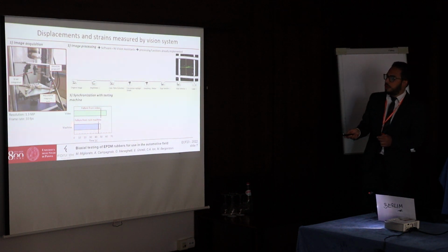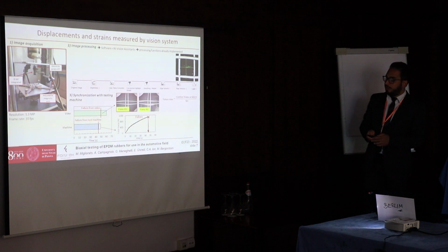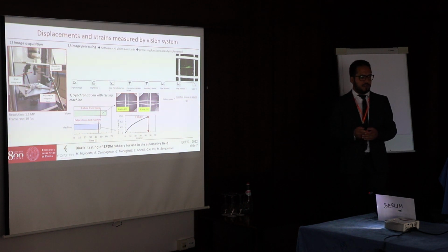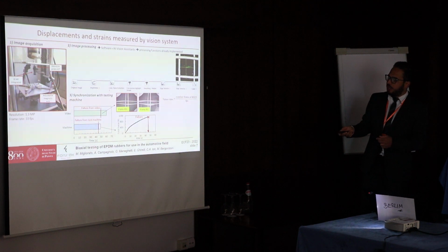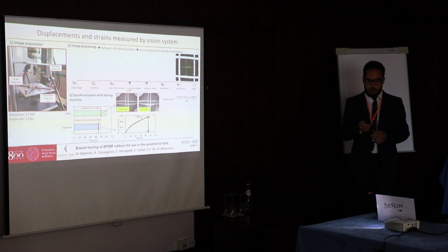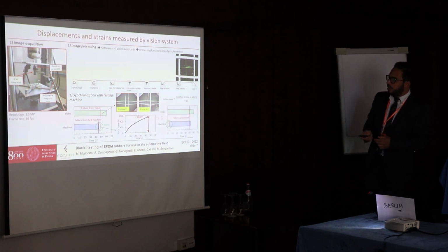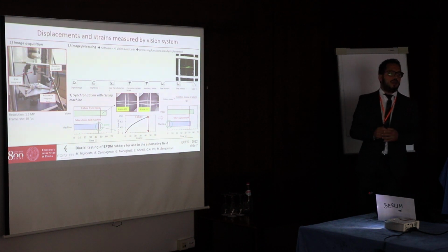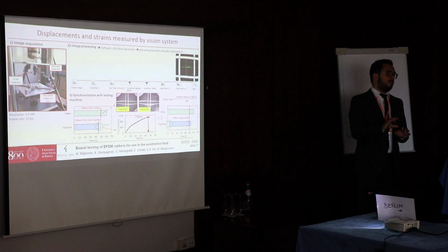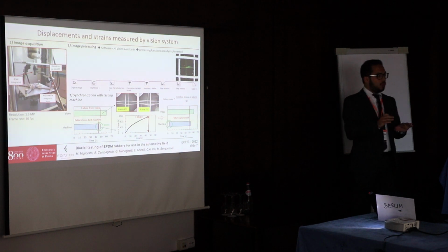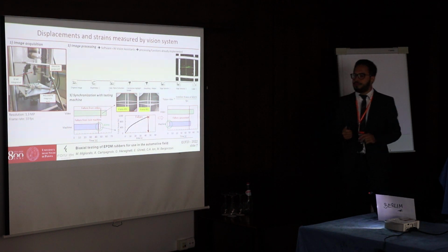Therefore, a synchronization has been performed on the basis of the failure phenomenon, which has been defined with reference to the video system as the frame where the incipient failure was observed, while for the testing machine, the failure phenomenon has been defined on the basis of a recorded load drop. Therefore, synchronization has been performed on this failure phenomenon, and at this point, for each frame, we know the displacement of the markers and also the strains, and importantly, we also know the relevant applied load.